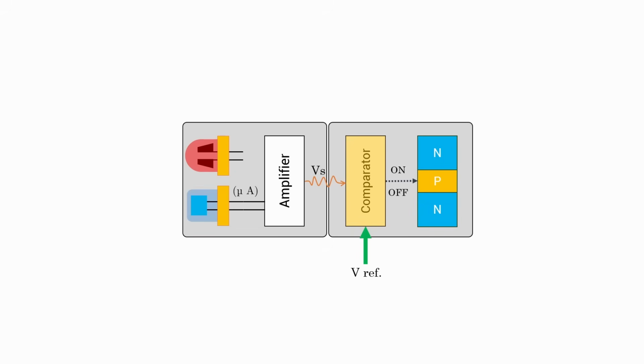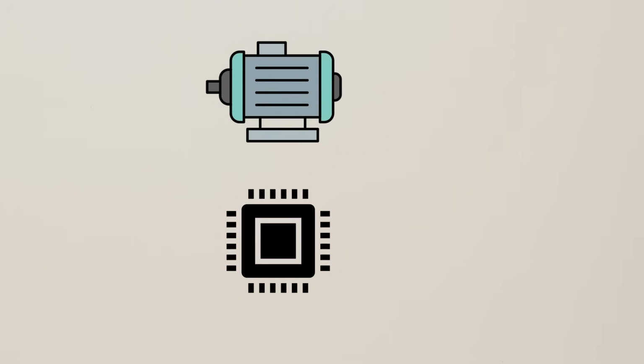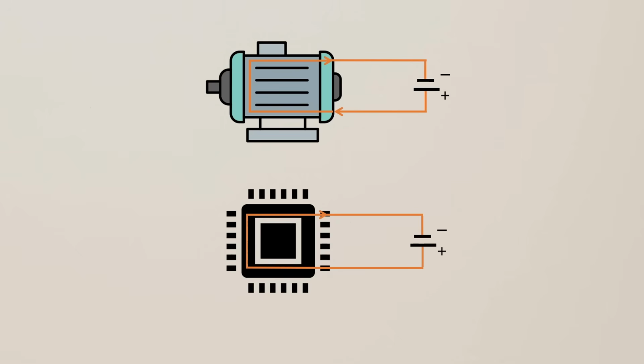Now, to understand which type of transistor output we should choose, PNP or NPN, we need to understand how they are wired and how the current flows differently. And this is usually the part that confuses most mechanical engineers. So let's go step by step from completely basic. How does any electrical or electronic component operate? Simply when electric current flows through it, right? And the current only flows when there's a complete circuit and a voltage difference.